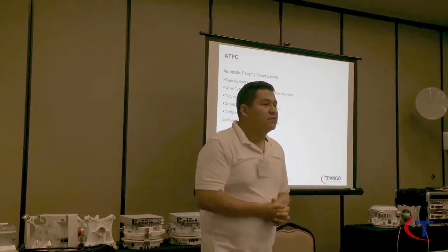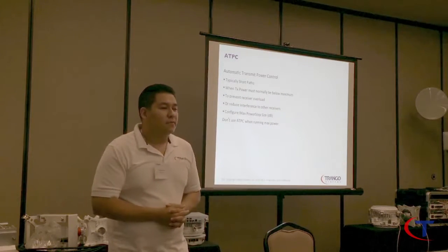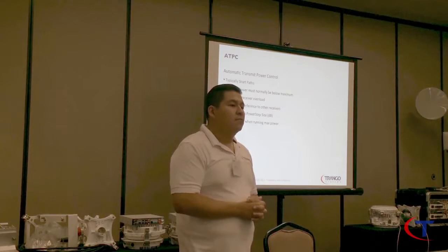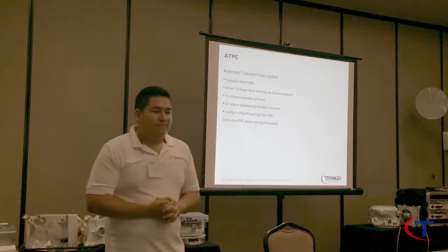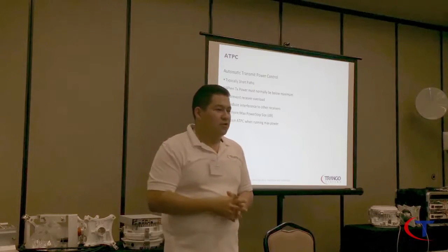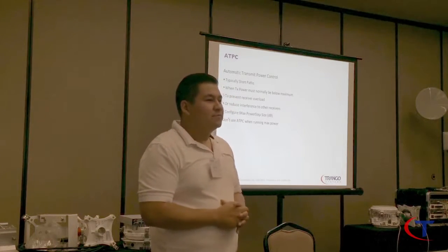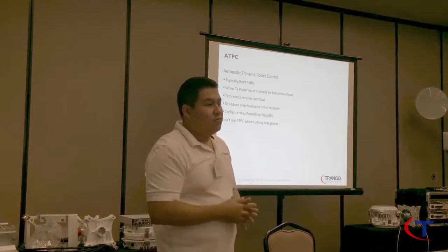If you take these radios and run them without an antenna on them, do you risk blowing the finals in the radio? No, these don't have that. You don't need a load at the end or anything. It's fine, because the transmit power is generally low anyway. You can keep it down, yeah.